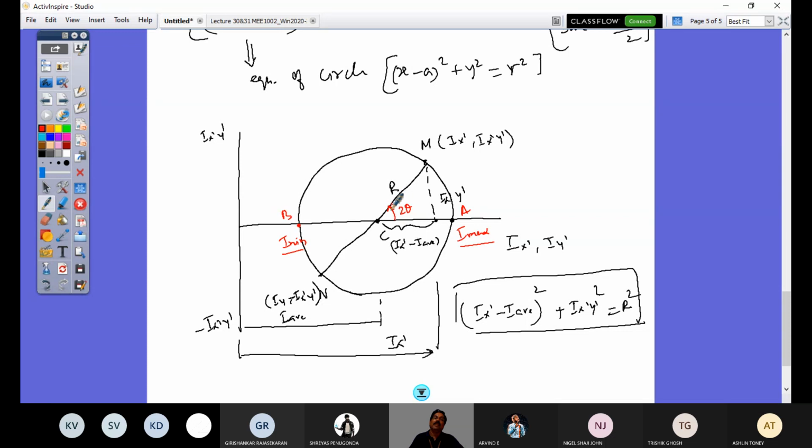So if I rotate this Mohr circle by 2 theta clockwise, my section here also should be rotated by the same angle. So I should rotate my rectangular section, or in this case some arbitrary section that we have, by an angle theta to have my x dash y dash axes give my I max and I minimum values, right?